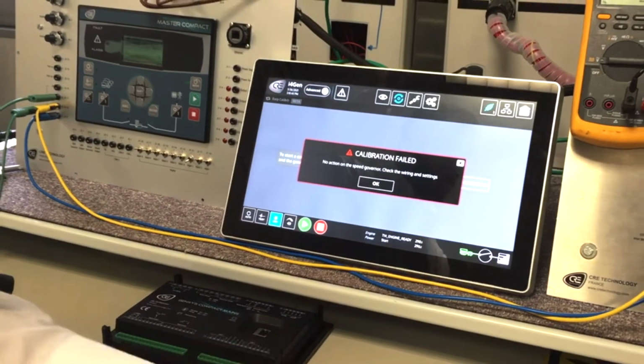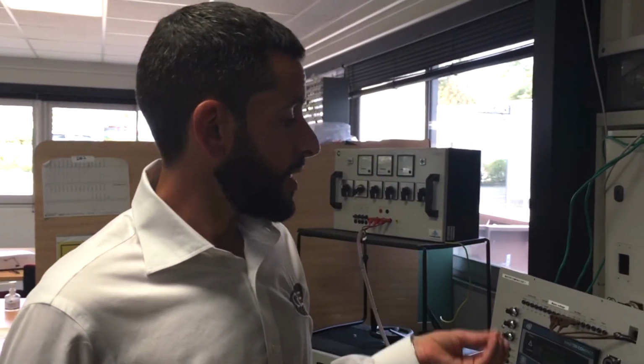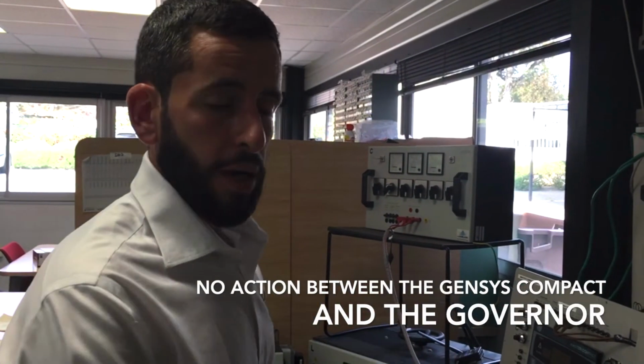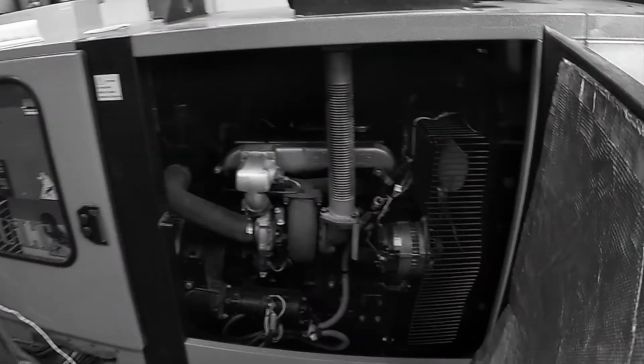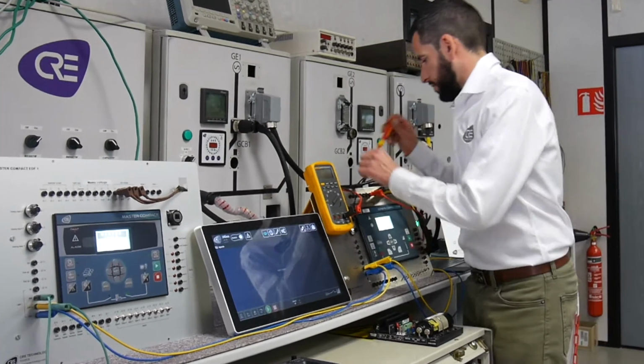So this is what I'll do now. I'll stop the genset, and indeed I have disconnected the wires of the genset. So it means that the action from the compact is not going on the governor at the moment. It is happening quite often during commissioning that this kind of wiring mistake is happening. So I will correct the wiring and we will start again the EasyCalib.